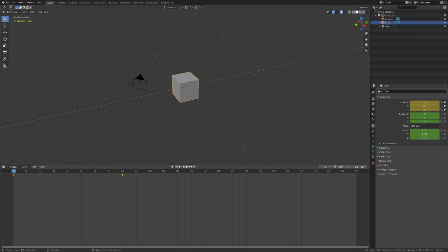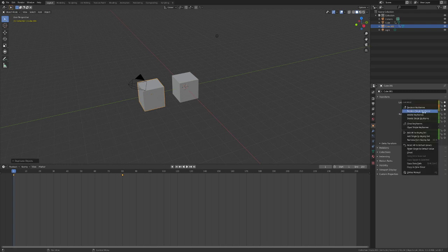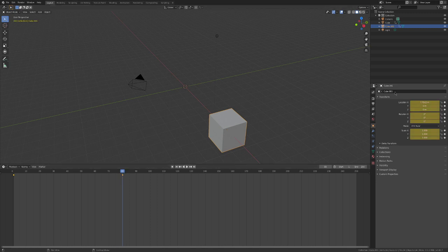And of course, I cannot do this like that because everything is keyed in that position. What I need to do in this case, it's actually getting more complicated than I thought, it's removing the keying of what I don't need. I don't need any keyframe on the Y, so I'll delete keyframe, single keyframe on the Y, and I'll delete single keyframe on the Y here too.